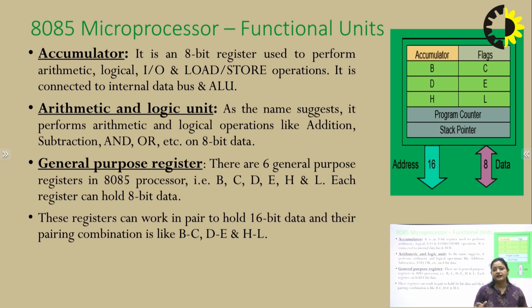In the register array, the most important register here is accumulator. As the name suggests, it is accumulator. In order to accumulate, we need to collect something. So, the name signifies that we are collecting something. Accumulator is a special 8-bit register which is used to hold the result of every arithmetic and logical operation. It is not only used to perform the arithmetic and logical operations, but also it is used to store the result of every ALU operation.